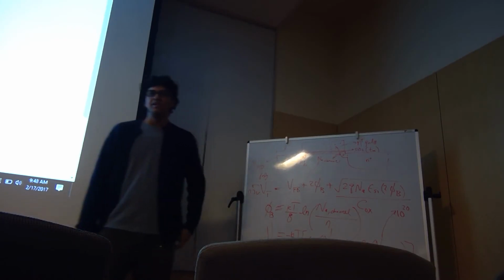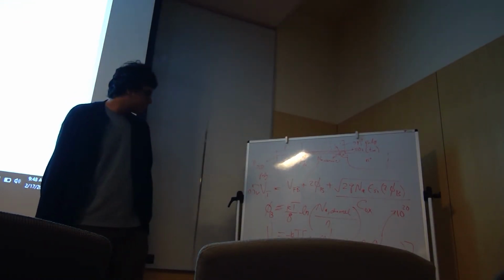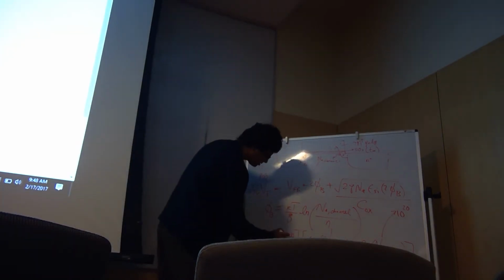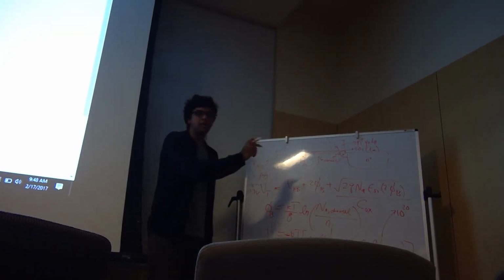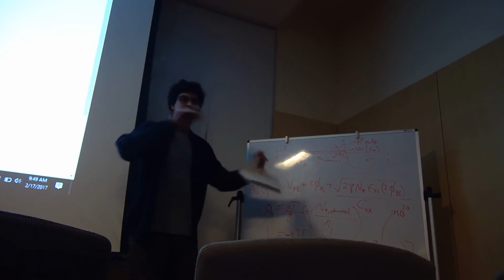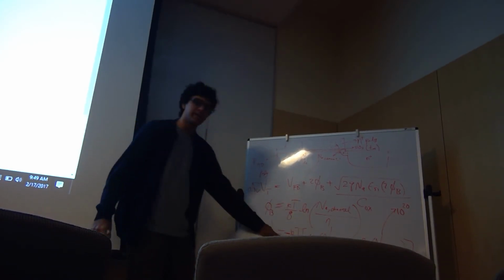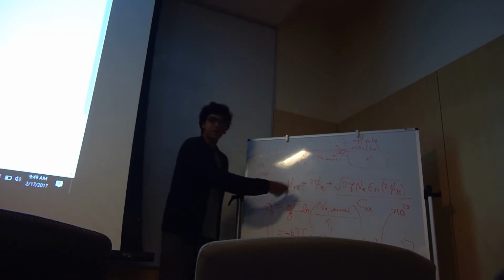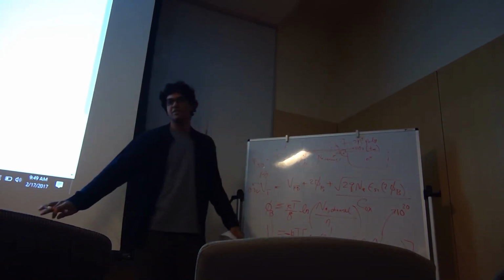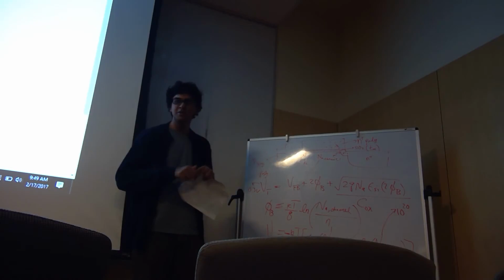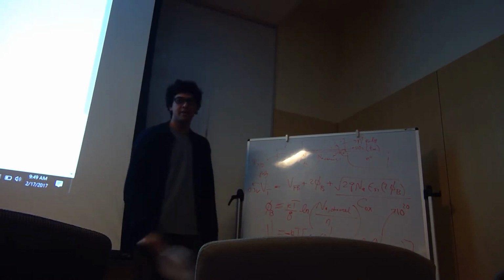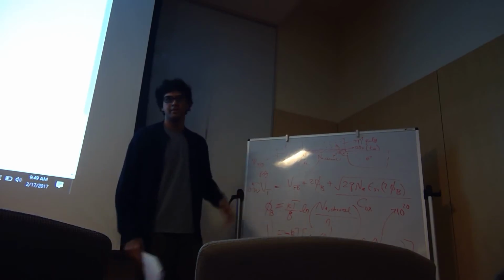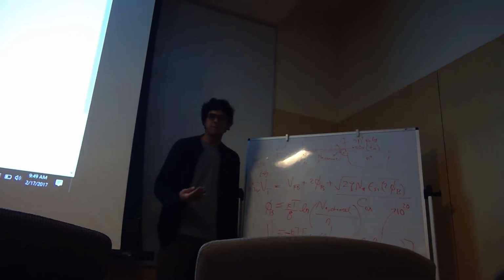So is that minus kT by 2? Yeah, it's negative. Because when you have an NMOS with this particular doping, you need to apply negative voltage to create the flat band condition. So that's why it's negative. Again, this is not arbitrary, okay? I repeat this now: for the PMOS, this will completely change, okay? So please make sure you use the right equation for the right case. And for the PMOS, you need to look for the donor doping, not the acceptor doping. So, questions?